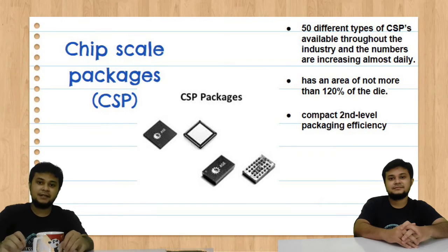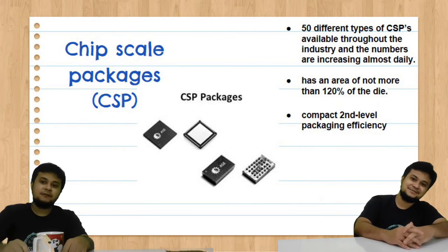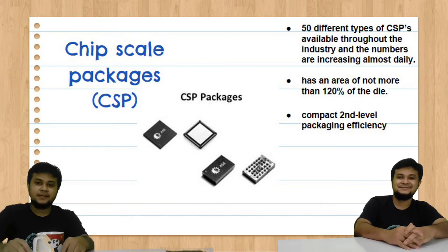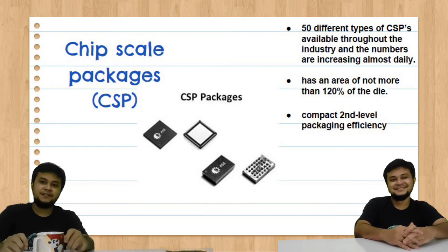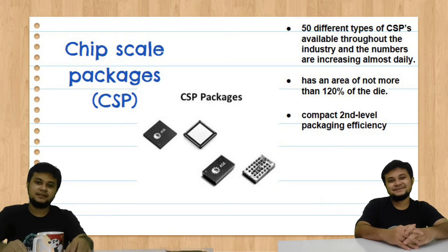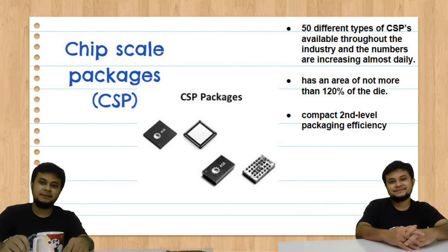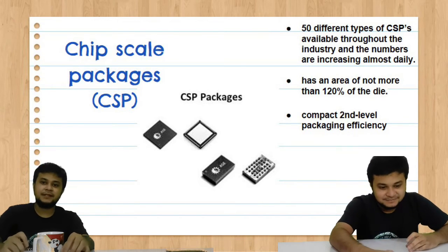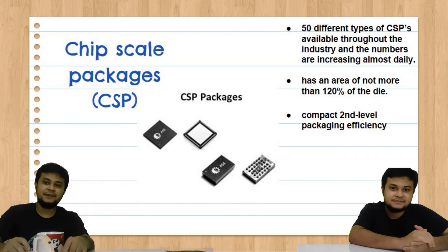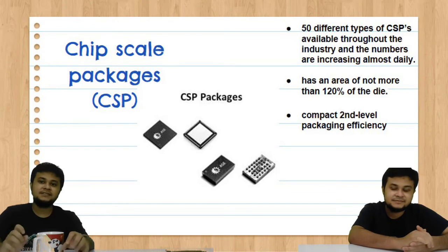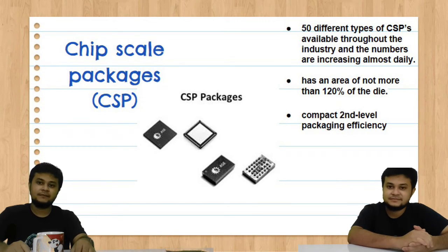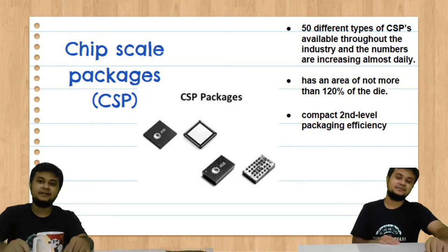Second, very good electrical and thermal performance compared to plastic over-molded packages. Third, utilizes standard surface mount assembly technology. Next, proven board level reliability (BLR). The disadvantages are limited package assembly data availability, moisture sensitivity, and thermal management that have high interconnection.